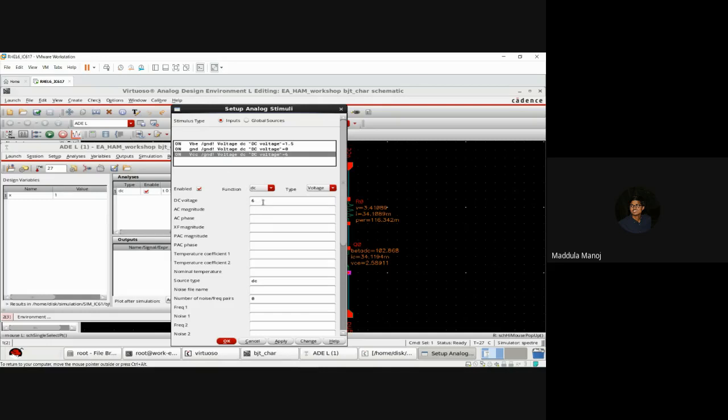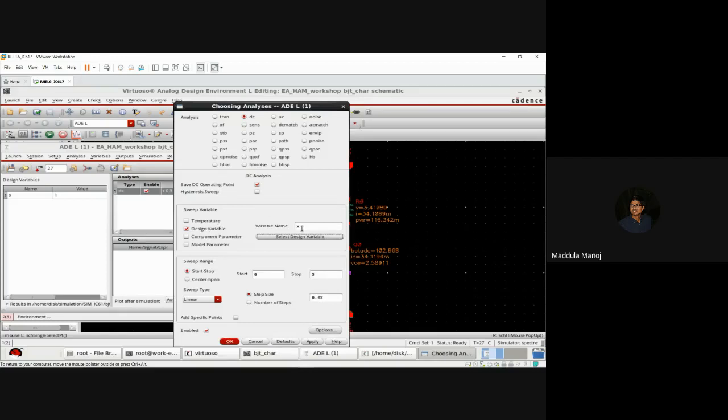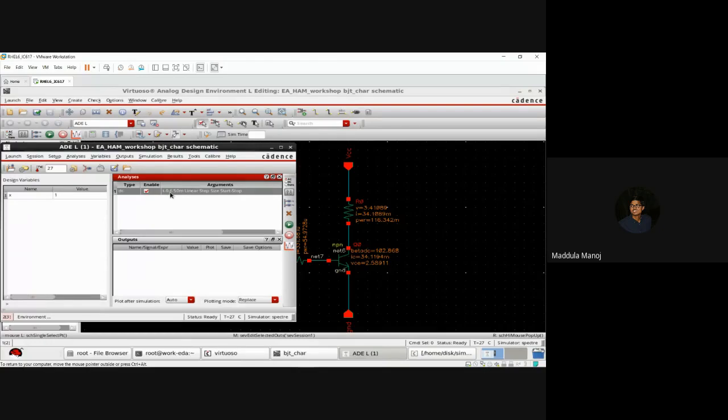And for VCC, let's say now we give VCC as X because we need to vary the collector voltage, right? So do this. VCC is given X, VB is given a constant input voltage of 1.5 volts. So now we need to change the simulation. Everything is the same. The design variable is X, but now the variable X is applied to VCC. So let us sweep up to 6 volts. We can reduce step size for faster simulation just for analysis. You can increase or reduce it, it's fine. Sweep type is the same, so we just change the range of simulation. Just click on OK. You can see it is sweeping from 0 to 6 with a step size of 50 millivolts, which is 0.05, in a linear fashion, right?